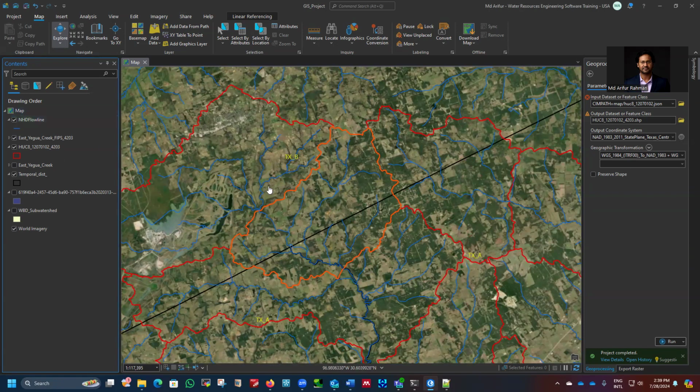And we'll also try to download the observed data set. If we have any USGS observation, we can process that gage data to calibrate our model, because this is a frequency storm. So we need to compare the 100-year simulation with the 100-year flow. So we need to either collect that data from regression analysis or from StreamStats, or we need to do the gage analysis.